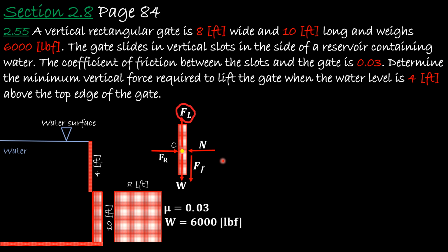So this resembles what? An engineering statics problem where we sum the forces in the x, in the y, and we sum the moments to help us find the different forces that we need to find. So here, let's sum the forces in the x direction. Let's say going to the right is positive and going to the left is negative.